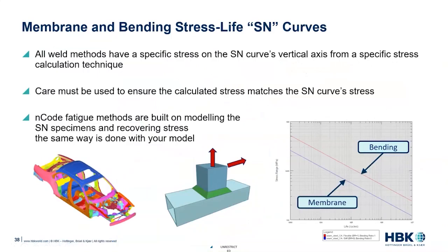So all of the spot weld and seam weld methods within nCode DesignLife have a specific stress on the SN curve vertical axis. We have to take care to ensure that the calculated stress matches the SN curve stress, which comes from testing.